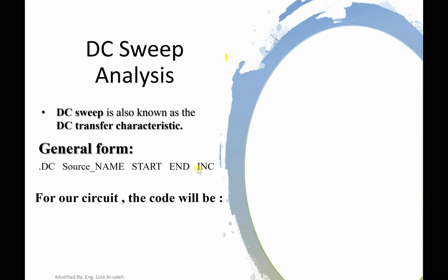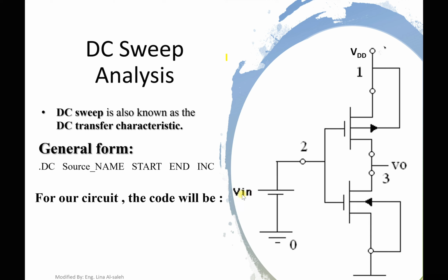For our circuit, we said that we wanted to sweep Vinput. We will sweep Vinput from 0 to VDD with an increment equal to 0.01.